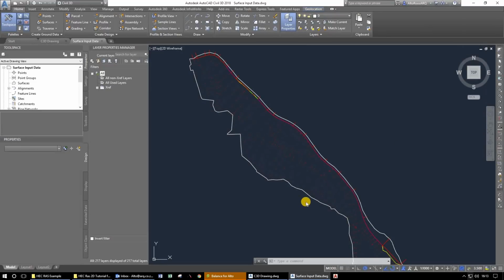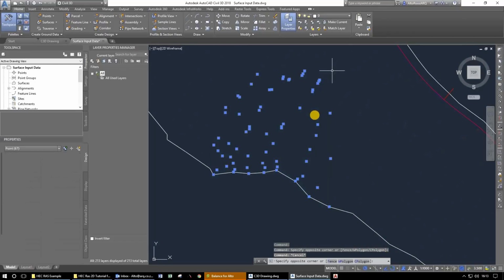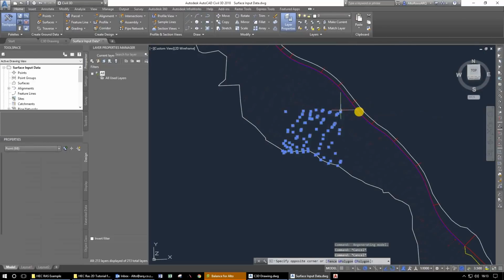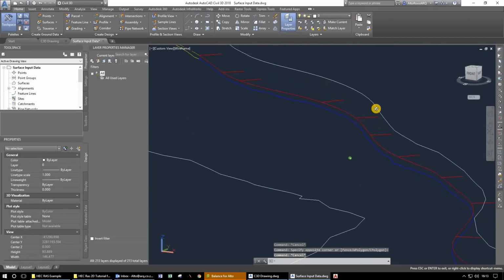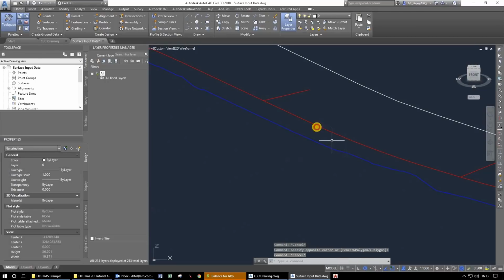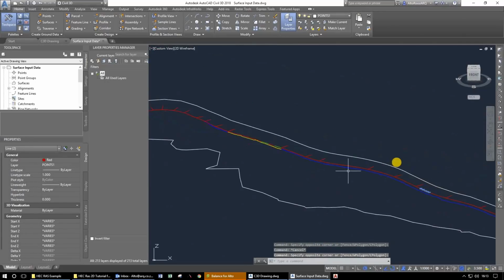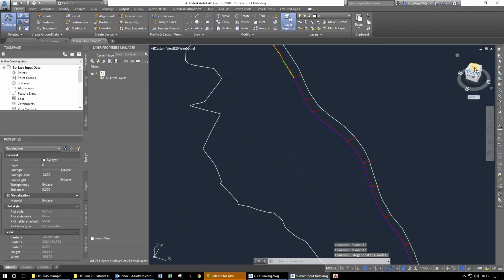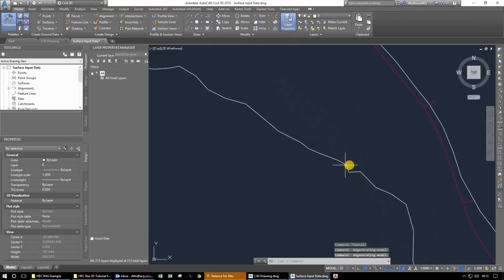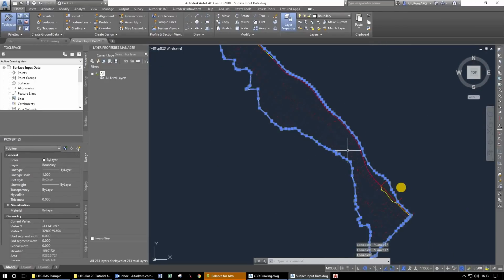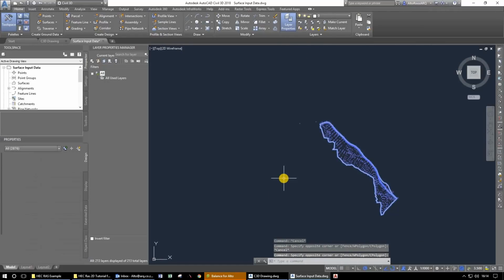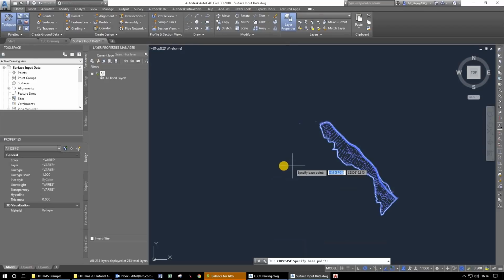As you guys can see, on this specific drawing we've got a bunch of points. That was obviously some guys did a survey, and I already created a few break lines defining the new road geometry along the road. So that will help us to define the surface more properly, and then I've got a boundary for the surface as well. All of this I'm just going to select by pressing Ctrl A, Ctrl Shift Copy. I'm going to copy it with base point 0, 0, 0.